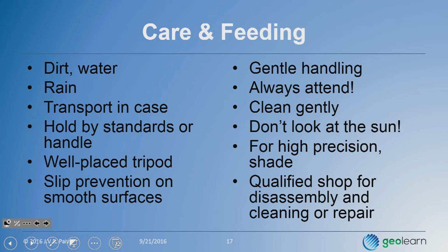There are various ways of doing that, and some of those will be discussed in lab. Instrumentation should always be handled gently. And what do I mean by that? Well, you don't slam it down on top of the tripod. You don't slam it into its case. You don't jam the case closed if the case doesn't close smoothly.